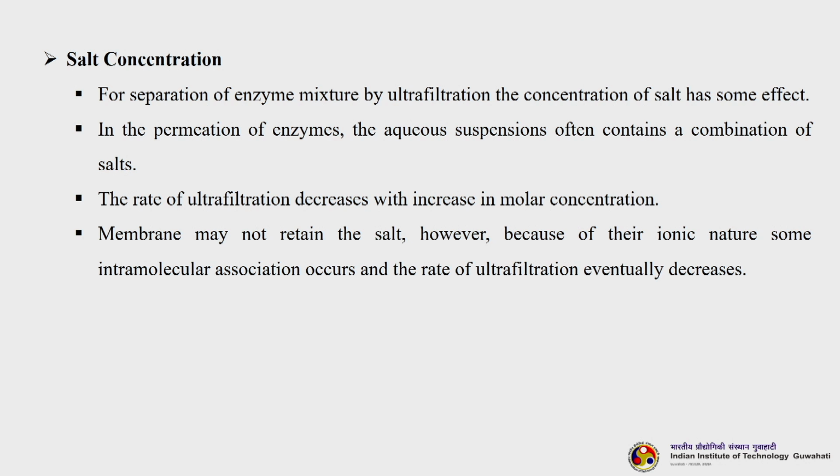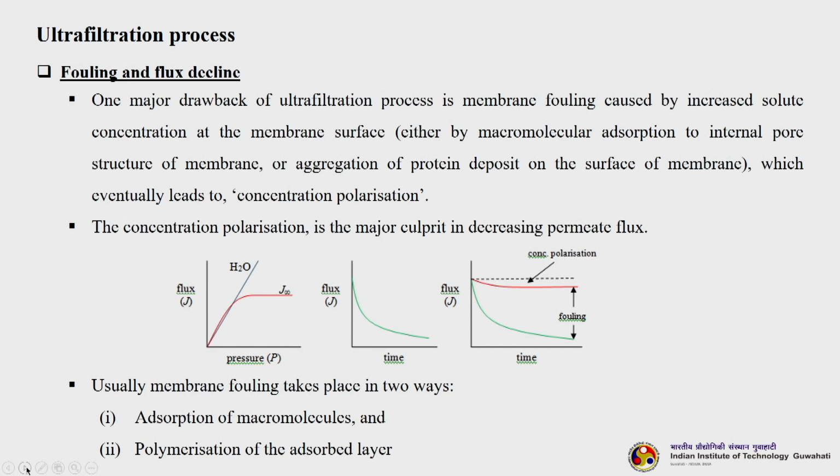The membrane may not retain the salt, however, because of their ionic nature, some intermolecular association occurs and the rate of ultrafiltration eventually decreases. Now, let us understand and discuss the fouling and flux decline profile in ultrafiltration. You know it is the same as in other processes also, but we will quickly go through it once again, so that it will also revise your understanding of the flux decline performance as well as fouling.